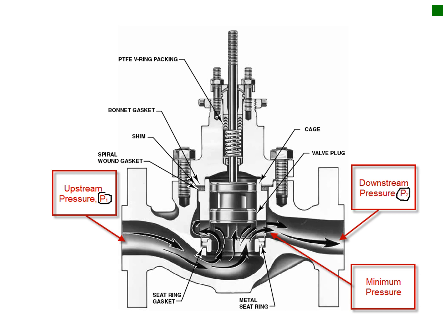One thing that we need to be aware of, coming out of the fixture in the valve, is what's called a minimum pressure. This minimum pressure is important to know because if we have a liquid that's close to its boiling point or its bubble point, that liquid may flash into a vapor, which will restrict the flow.